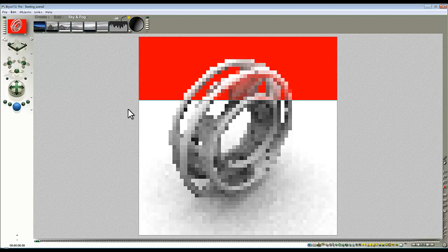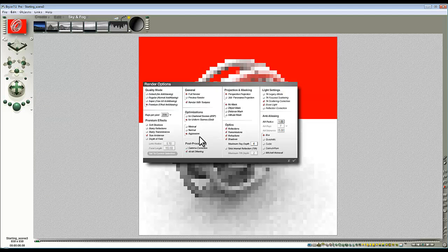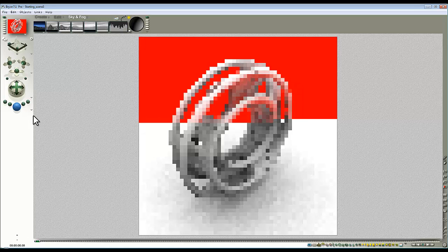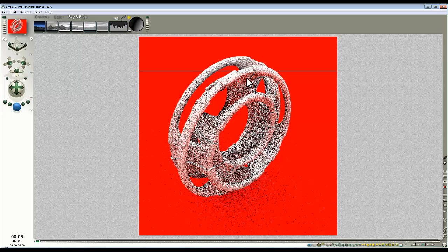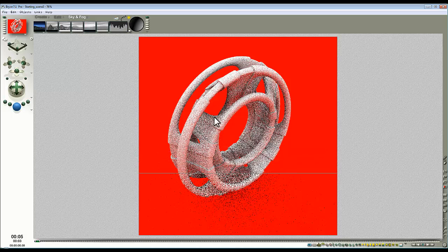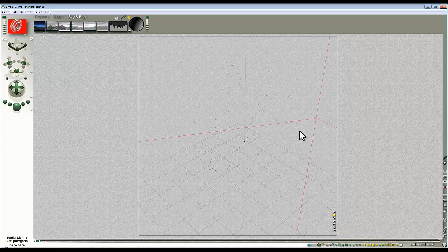I'll give that a quick render now. It's going to take a while because I've got the rays per pixel set up for final rendering, so I'll take that down to 4 rays per pixel now. You can see that at this level, well, it's a bit bright because it's default grey, but the red on the ground is getting transferred onto the surface, so it's operating back in the light gathering mode where it's able to transfer colours from one surface to another, which is good. But there is yet another trick we can do.